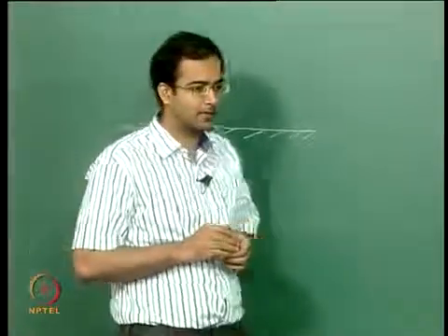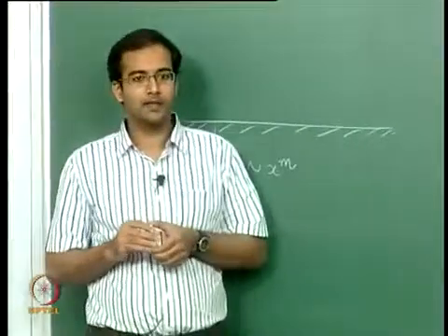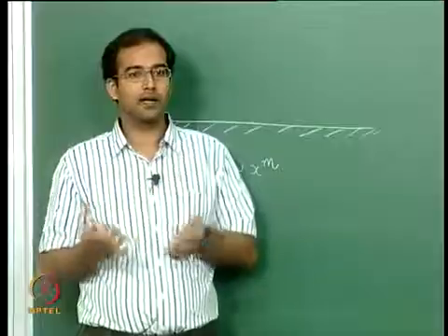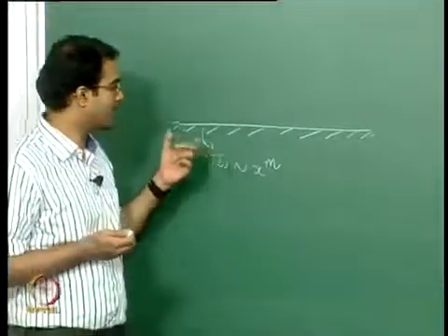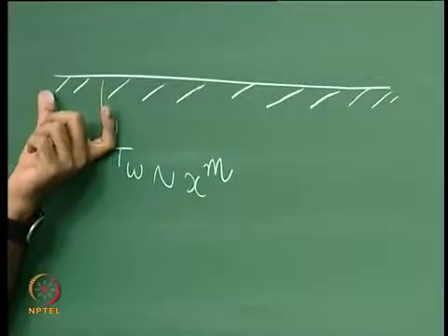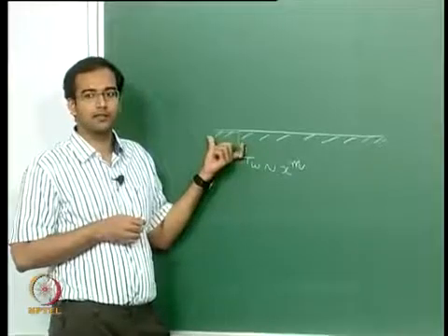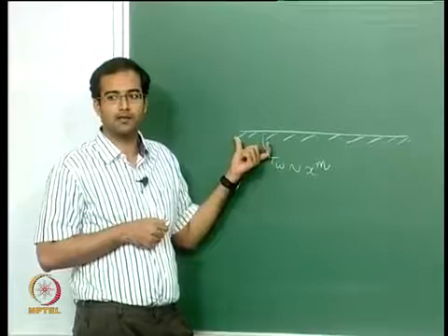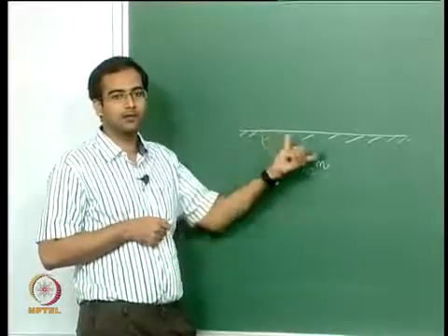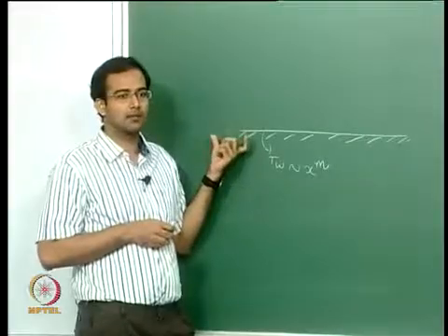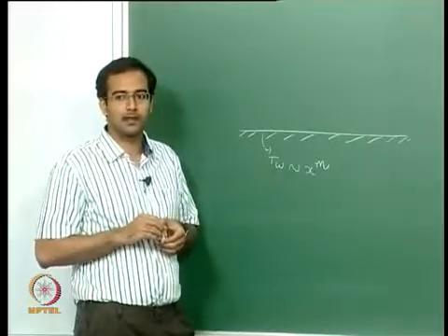Okay, the approximate methods give you a lot of flexibility in approaching problems with different kinds of boundary conditions, and also things like where the boundary condition has an unheated starting length. Okay, so there is no similarity solution if you have an unheated starting length. So these kind of problems with the variation in the boundary temperature and the heat flux can be easily solved using the approximate solution.